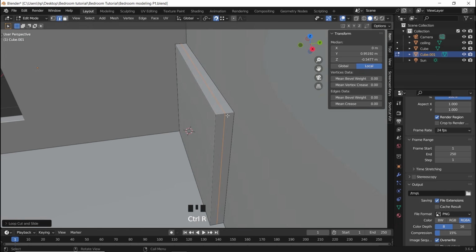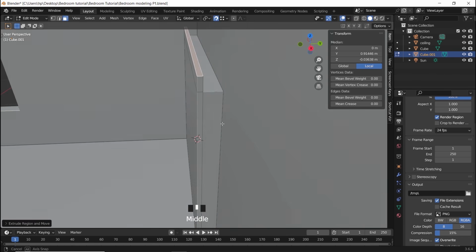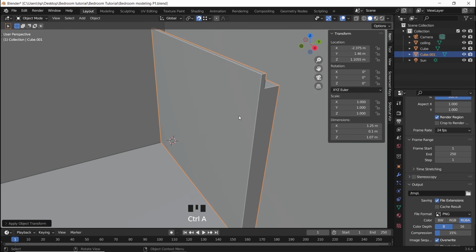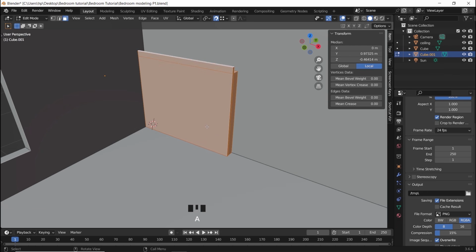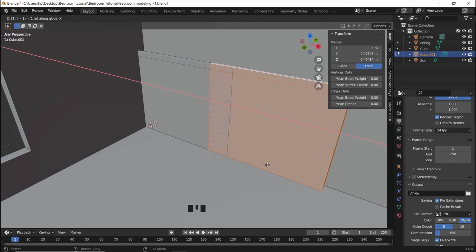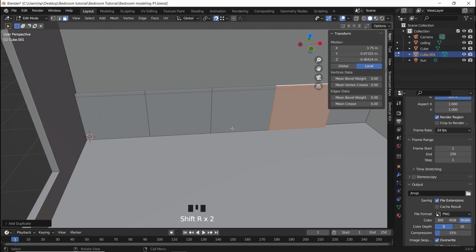Let us add a cut on this piece to make a hidden place for the light, then copy the mesh in edit mode 3 times so we end up with 4 pieces. Once you're done, add a bevel modifier to the mesh to smooth the edges, and always remember to apply Scale with Control A in object mode if you're using any command or modifier on any mesh.